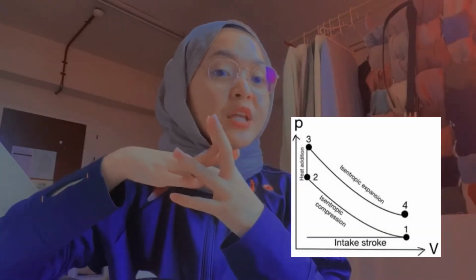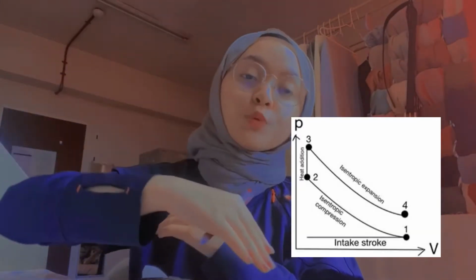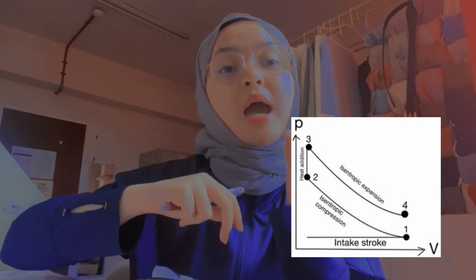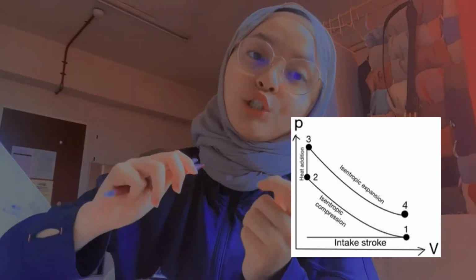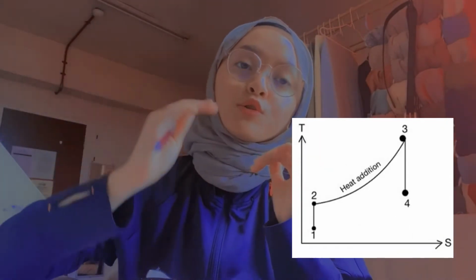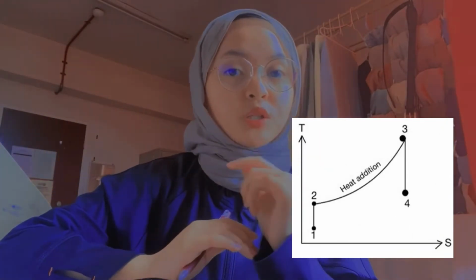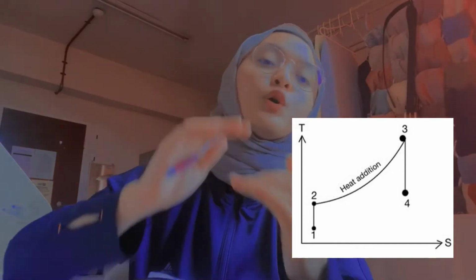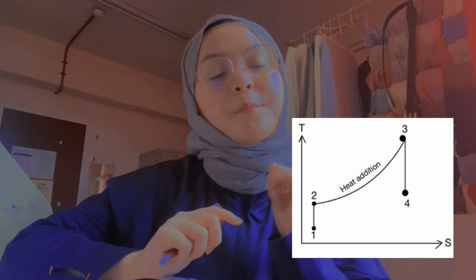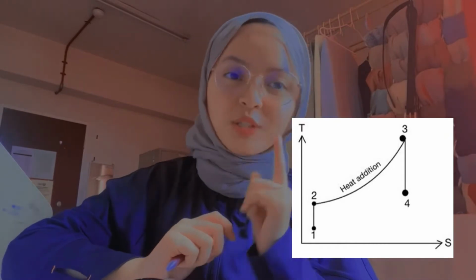As for the fourth phase, the piston head will go down and cause some loss of pressure. Due to that, in the PV diagram, pressure 3 will drop to pressure 4, causing some isentropic expansion, the same isentropic process from S3 to S4. And because of that, the temperature will also decrease, as pressure is directly proportional to the temperature.